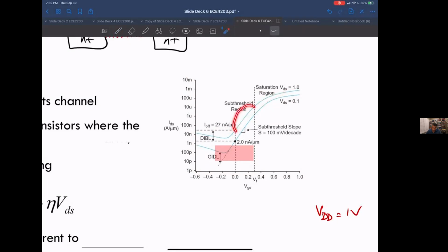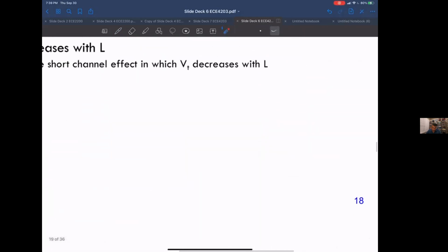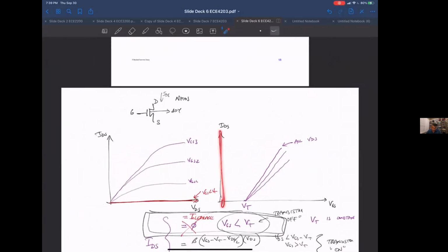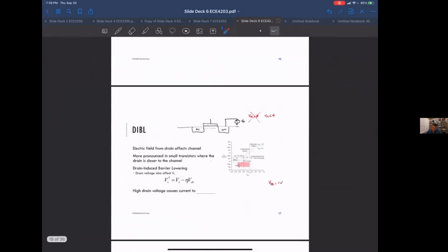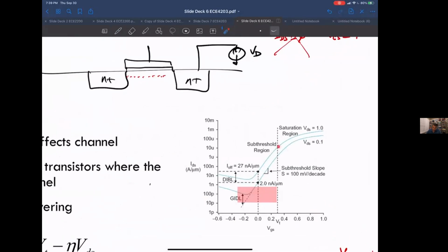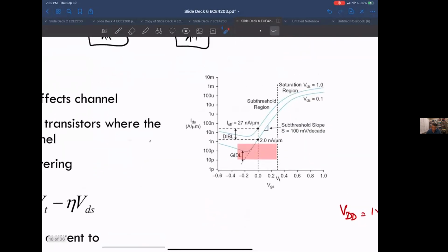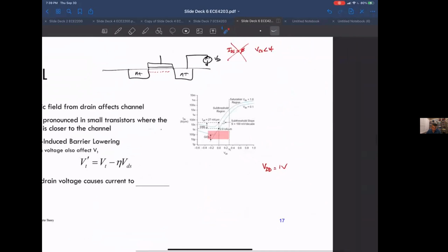Okay, and it's really zoomed in to this area around the threshold value, so you can see that it doesn't turn off. Even if I made this a log scale here, if it really went to 0, this whole curve would move down to wherever 0 is. I guess it never quite gets to 0 when you do log, but hopefully you see what I mean. But anyway, this is because of the nanometer process. So here's this drain-induced barrier lowering.